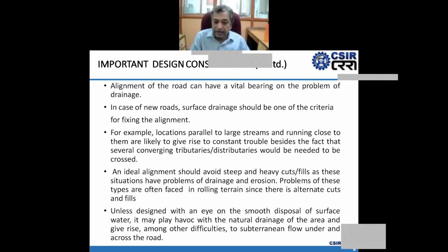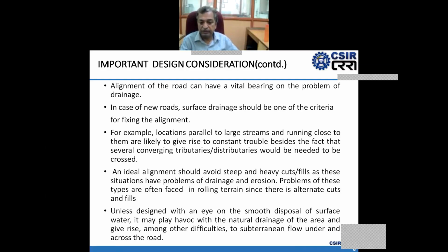Unless designed with an eye on the smooth disposal of surface water, it may play havoc with the natural drainage of the area and give rise, among other difficulties, to subterranean flow under the crosshead.